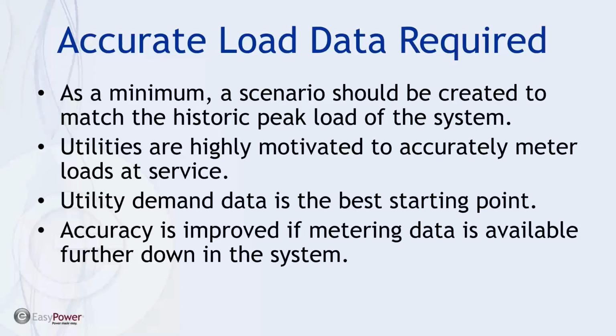And in the real world, that may not be the case. So what we need to do is tune that one-line diagram content or loading profile to match what our actual system is. And there are several sources of data that can be used to refine the model.